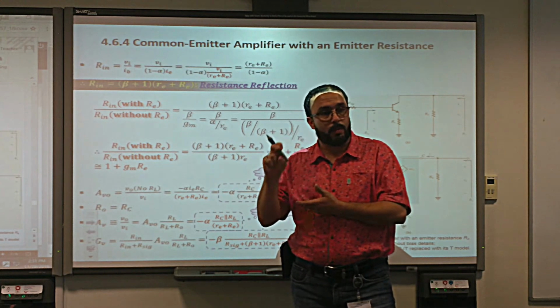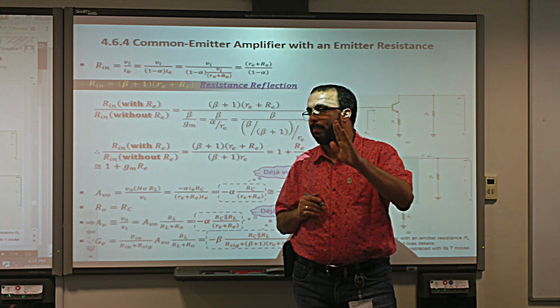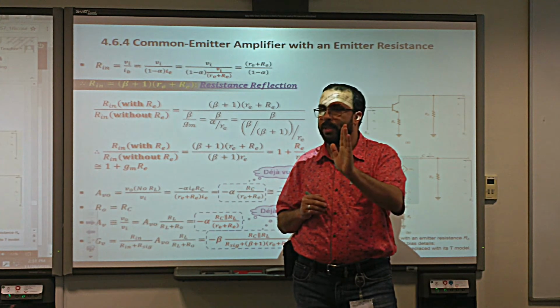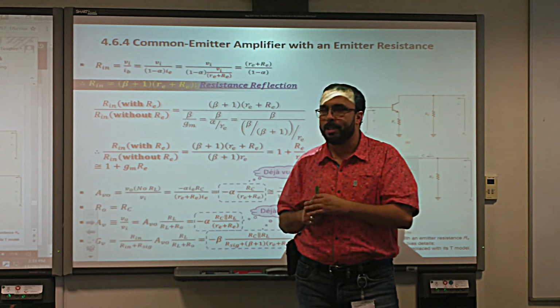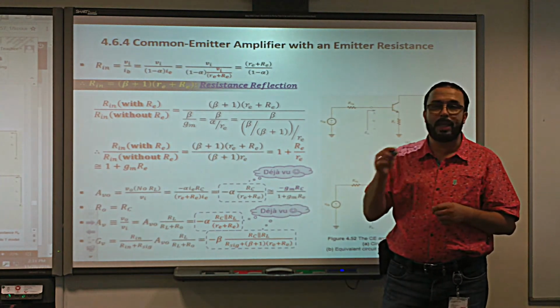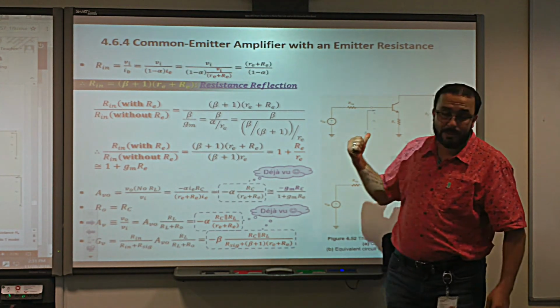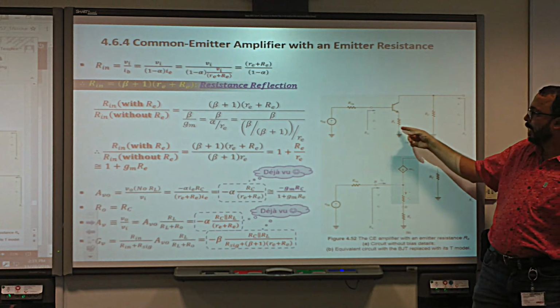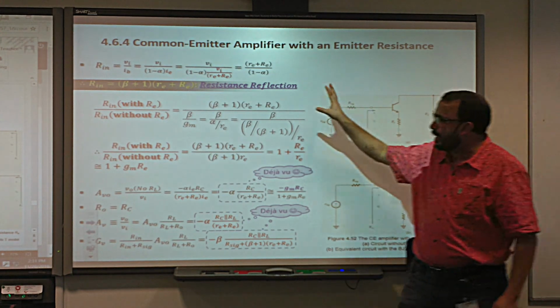So that resistance, when you put it at the source when you use a MOSFET, stabilizes the quiescent point. You make it stable, meaning that if there's any change in the threshold voltage, that change will not change the bias point. We put it purposely there, and we call it negative feedback, if you remember. Here it's the same story: we also put a resistance at the emitter to stabilize the operating point, or the quiescent point. So let's study this.